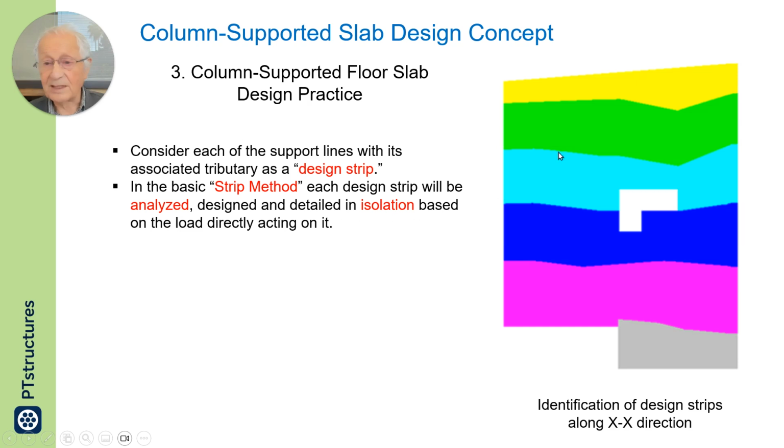In this method, if there is a load here where the cursor is positioned on the green design strip, it is assumed that the load is carried by this strip. It is not recognized that some of it will come to the light blue, and in reality, it will be shared between the green and the blue. But that's a different story. As far as the method,